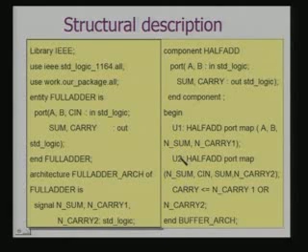And then the actual architecture, this is the definition part, architecture is U1 consisting of U1 and U2, which does a port map, okay, fine, and it is now defining the carry. So this is completely defining my full adder as a connectivity between the two half adders, okay. So here if you see that half adder, it is doing a port mapping.